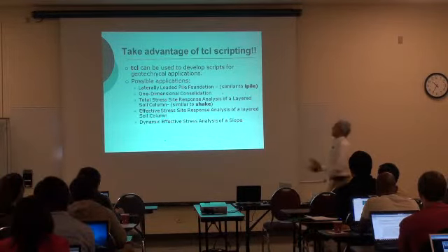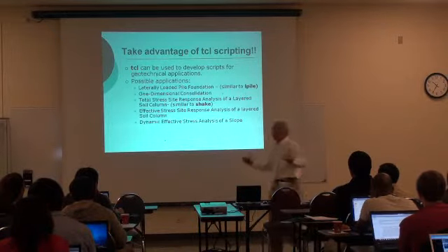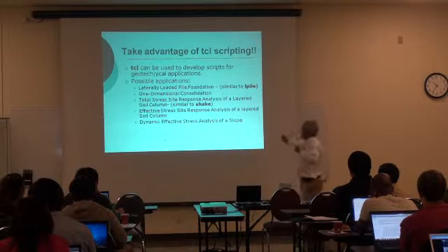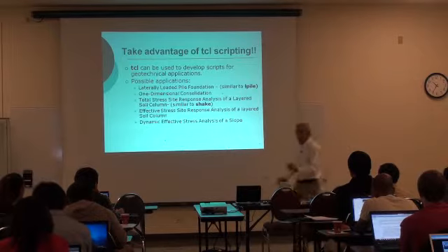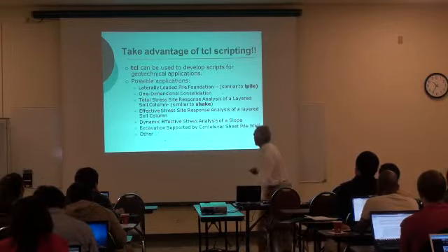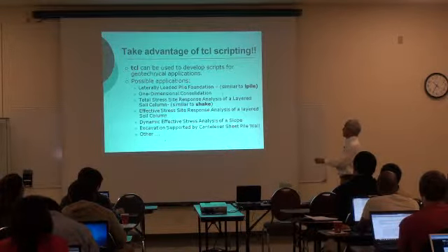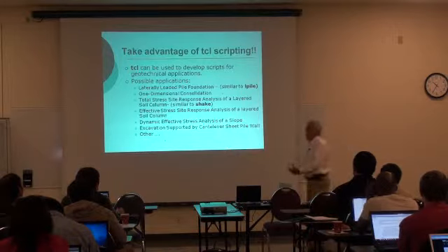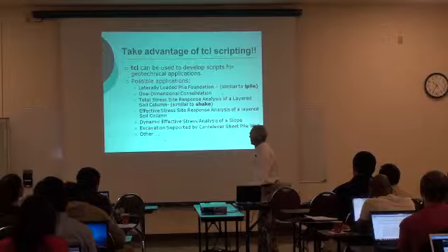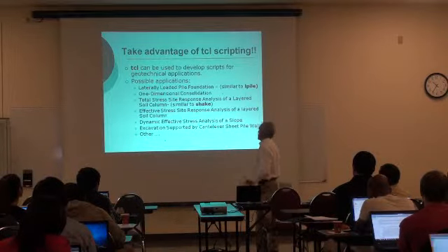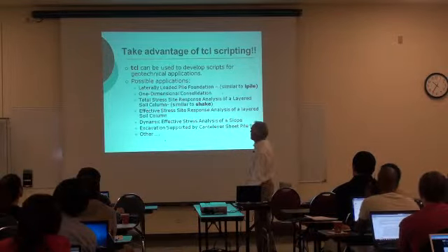Then dynamic effective stress analysis of a slope. Now you're really reducing to finite element codes, for example, Plaxis, FLAC. You can use Abaqus, of course. But with OpenSees, now you are in the domain where things can only be done here. Excavation, excavation supported by cantilever sheet pile walls. So now you're dealing with problems that can only be handled using finite element tools, and OpenSees is one of those. So the idea was to develop a couple of these scripts that could help you starting with these type of things.